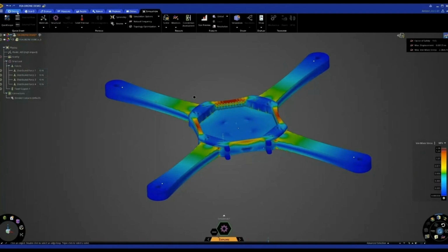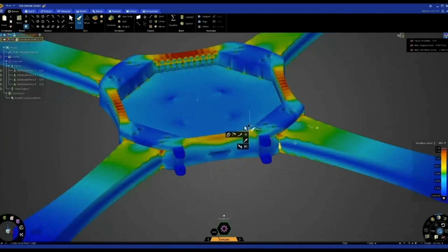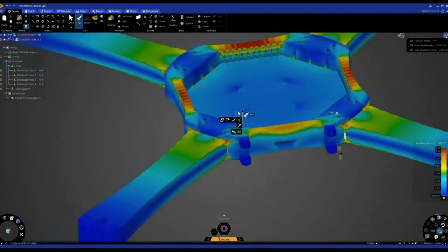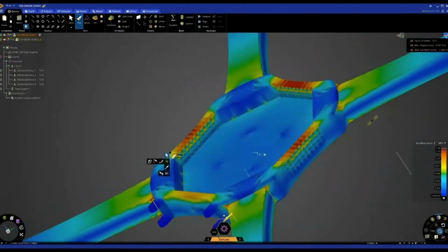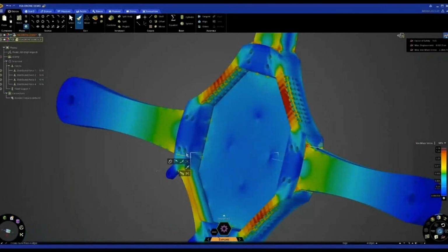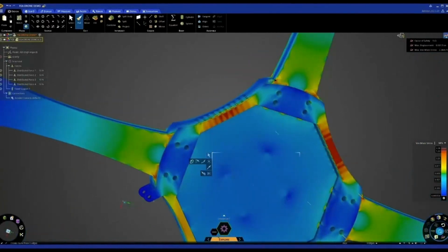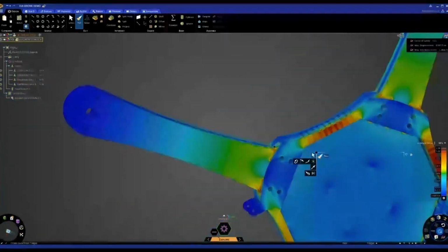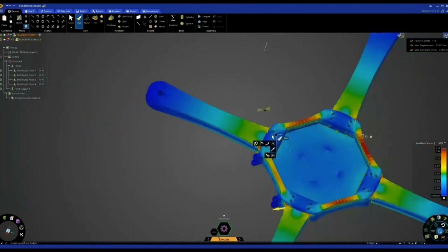If I go into the design tab, one of our 4 main modeling tools is the pull tool. So if I select on these edges, at the moment they're just sharp edges. We all know generally rounded edges will hopefully be slightly better. So I'm just holding control, going through and selecting on these edges. Forget the edge, not the point. Okay, so I've got all the edges selected.